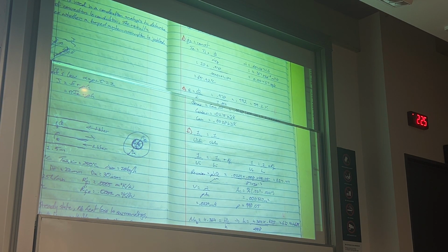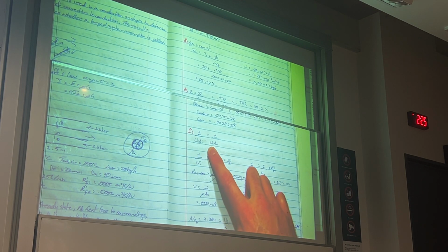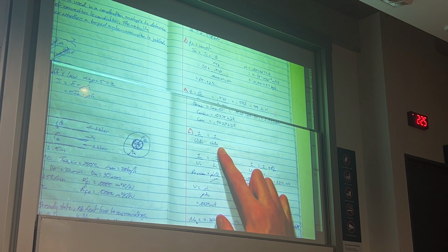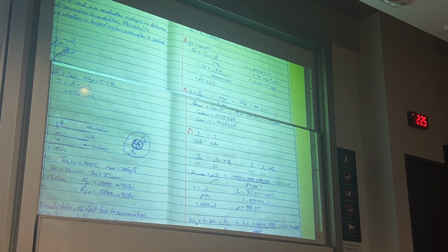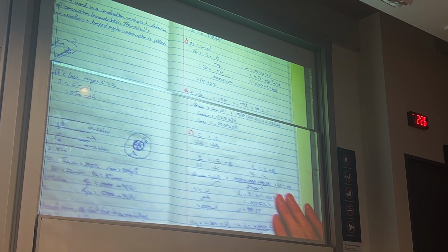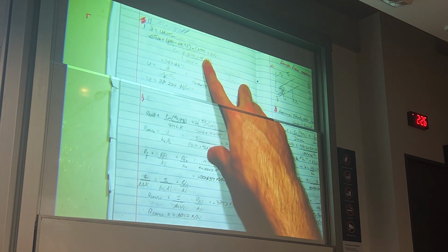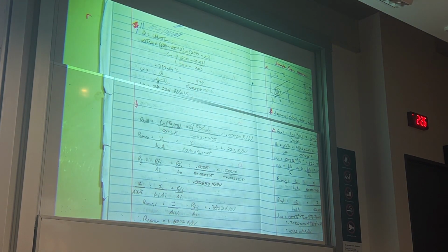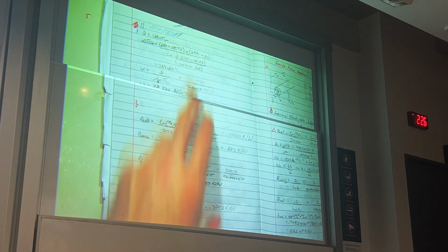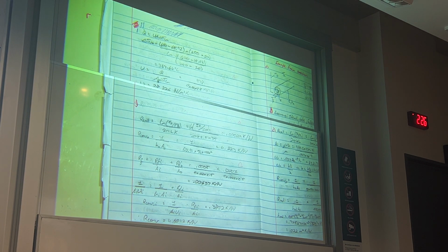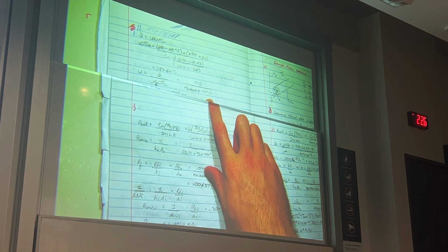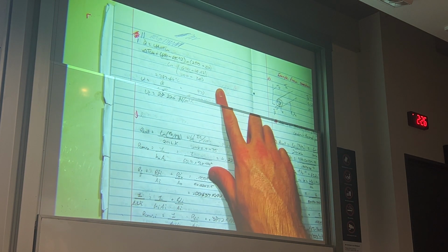So what I've done is, you can use this relation here because we've got U outer and we've got A outer. We can then go ahead and solve for U inner. Oh, sorry, no, I haven't missed that. And then I've used this relationship here, and I found my log mean temperature difference, and I've gone ahead and solved for U inner in this fashion here.